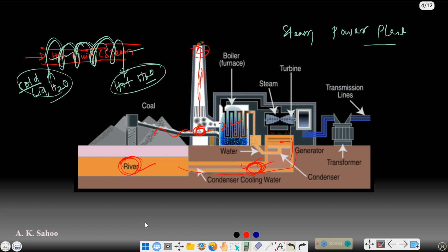Right? And if we are trying to learn what forms of energy our steam may have, we already know that there is the enthalpy, plus kinetic energy v square by 2, plus potential energy gz. This enthalpy is associated with the temperature.